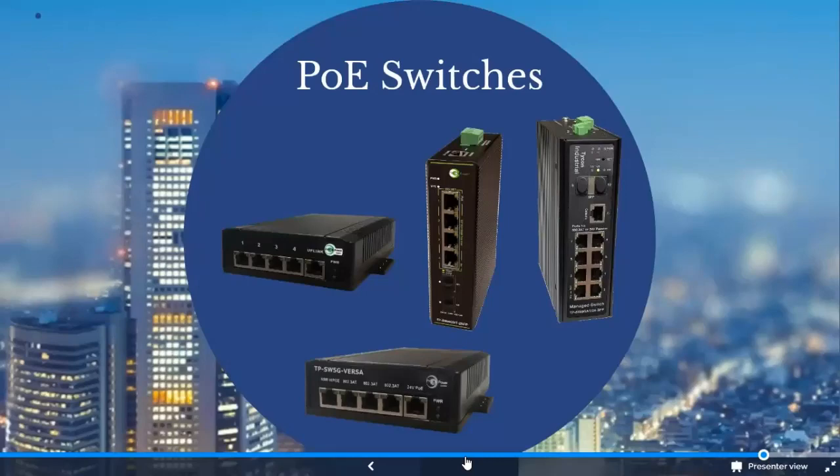So our switch here that's on the left is our SW5G-24. That's the one I'd mentioned before, that accepts 9 to 36 volt DC and will convert to 802.3 AT power on 4 ports with your data uplink as that 5th port.